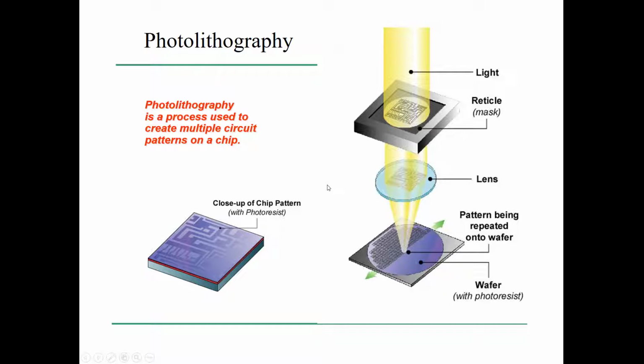Now, one difference between PCB and IC fabrication in this regard is that with PCB fabrication, the photoresist is most often negative photoresist that hardens when it's exposed to UV light. With ICs, positive photoresist is typically used. And positive photoresist becomes softer when it's exposed to UV light. So you have positive photoresist that's placed on top of the silicon wafer, and then the image.